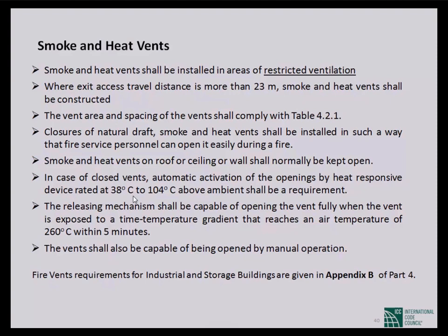That activation mechanism will work on the temperature or on sensing the smoke. The vent shall be capable of being opened by normal manual means. Whether I put in an automatic sensor or not, it must have something which we can operate mechanically.